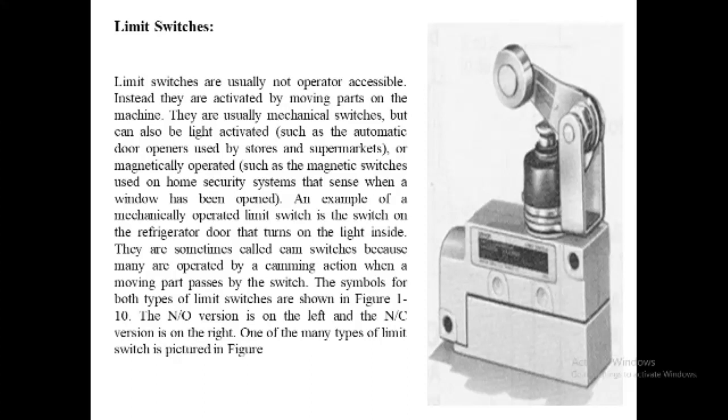The term limit switch is derived from the operation of the device itself, as the object, or sometimes it may be called a target, makes contact with the operator of the switch, and it eventually moves the actuator to the limit where the electrical contacts change their state. Through this mechanical action, electrical contacts are either open in a normally closed circuit or closed in a normally open circuit. Inductive proximity, capacitive proximity and photoelectric sensors perform this same process through non-contact sensing.